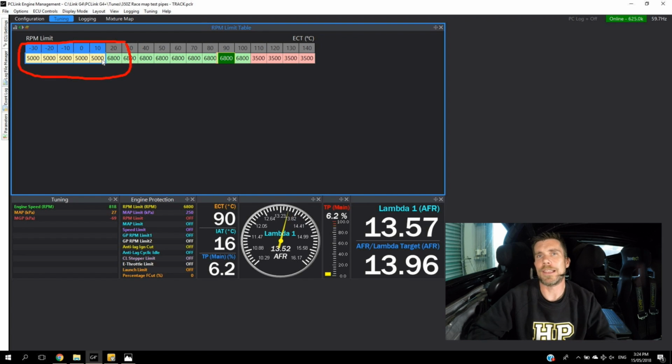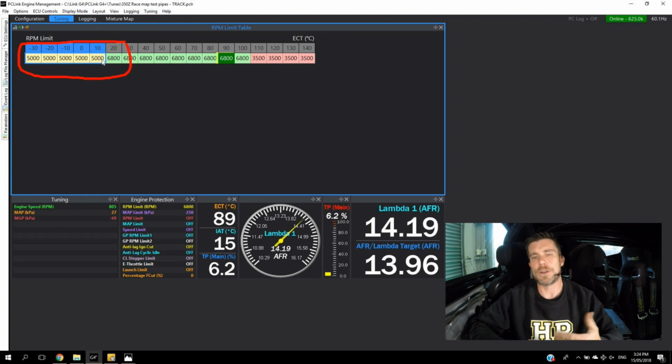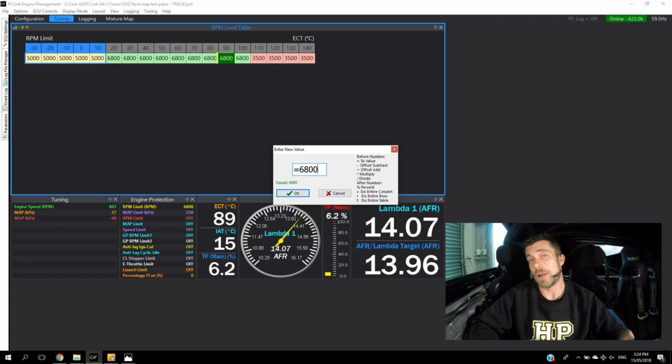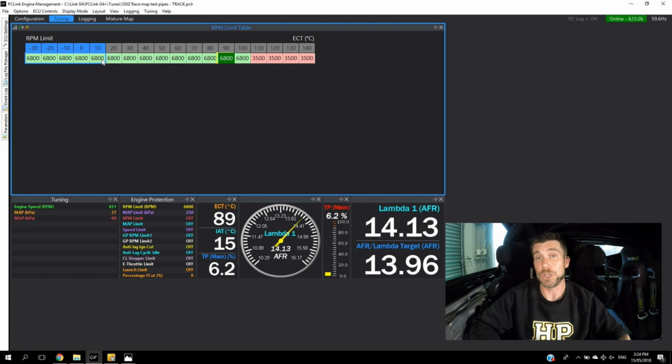So rather than allowing the customer to start the engine from stone cold in the middle of winter, head out of the garage door and then floor it straight onto the normal engine rev limit, we're going to potentially restrict that rev range until the engine is up to temperature. So again, there's no right or wrong way of approaching this. It really comes down to the individual and what you want to achieve here.